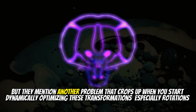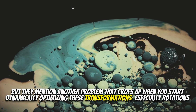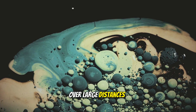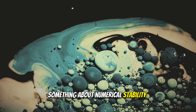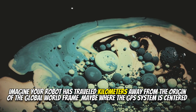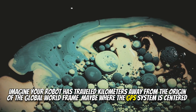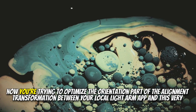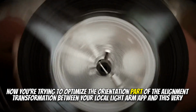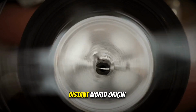But they mention another problem that crops up when you start dynamically optimizing these transformations, especially rotations over large distances. Something about numerical stability. Yeah, this is a really practical issue. Imagine your robot has traveled kilometers away from the origin of the global world frame, maybe where the GPS system is centered. Now you're trying to optimize the orientation part of the alignment transformation between your local LiDAR map and this very distant world origin.